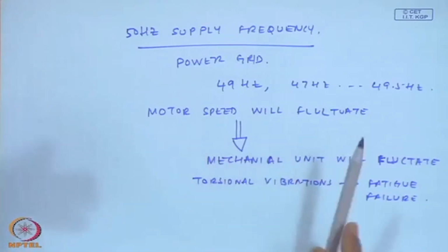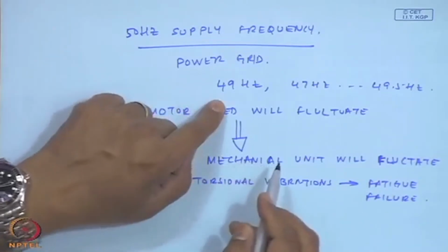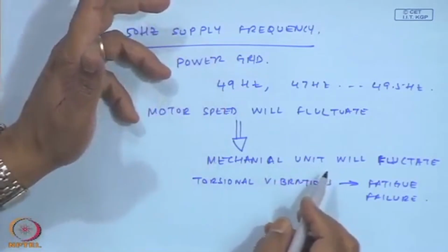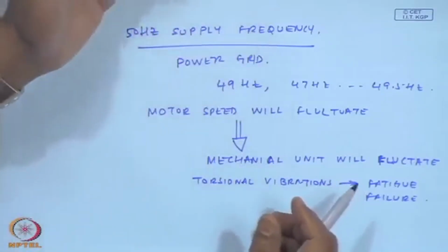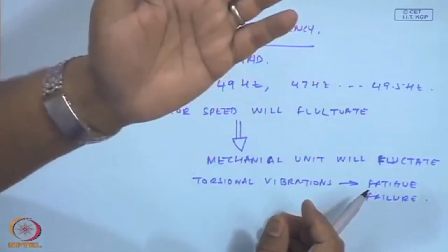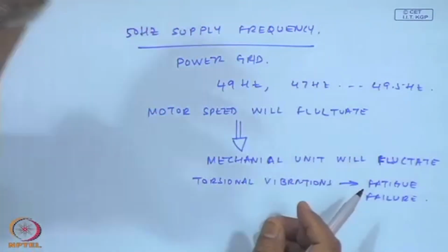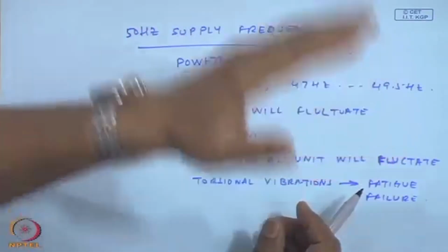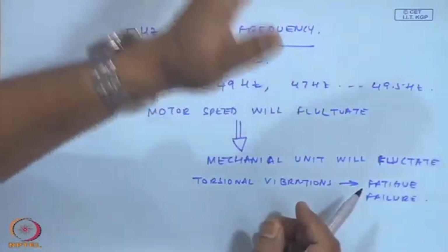Of course, in modern machines there are many safeguards to prevent that. The system itself will trip. You have seen how grid failure had a domino effect: one by one the grids fail. If the grids fail and you do not take up the load, the speed and frequency are again going to increase. So, in a power generation plant, they always have to maintain a balance between the load and the production rate.